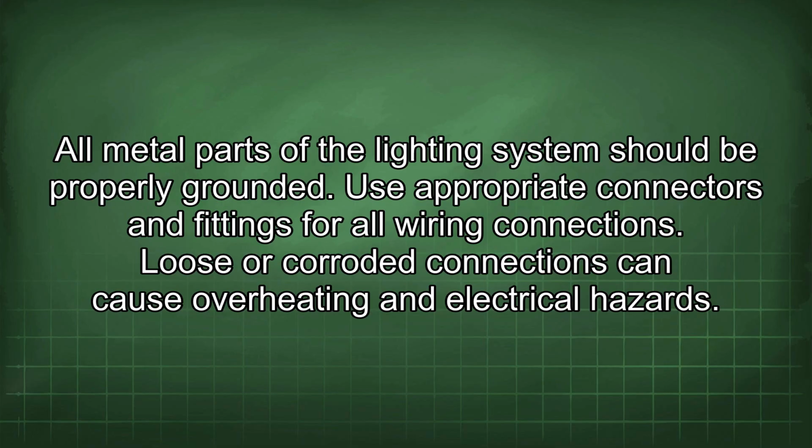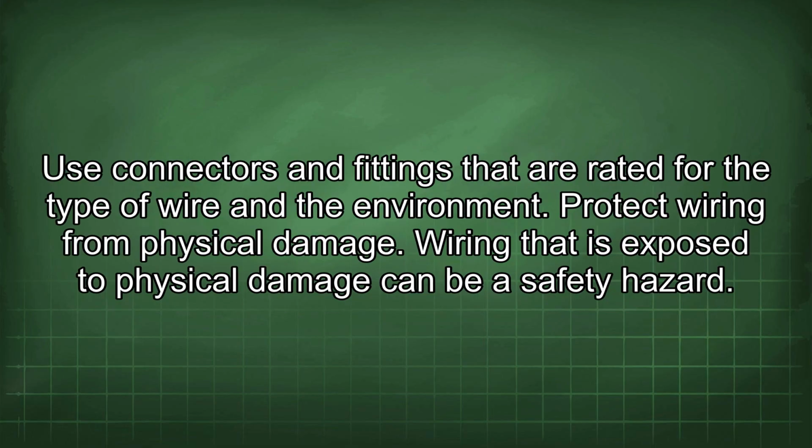Use appropriate connectors and fittings for all wiring connections. Loose or corroded connections can cause overheating and electrical hazards. Use connectors and fittings that are rated for the type of wire and the environment.